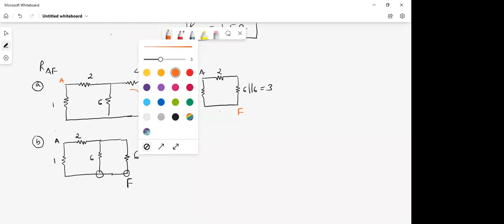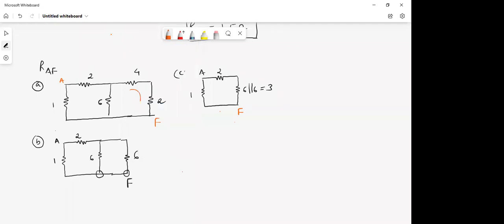Sir, also we have already calculated resistance between A and B. And B and F are shorted. Exactly, I was looking for that. That's why I purposely asked you all this question: what should be my first step, and I used the word conventional. So this is our conventional solution. The smart solution would have been the same as RAB, resistance between A and B, because point B, very good. I was just looking for this answer only.